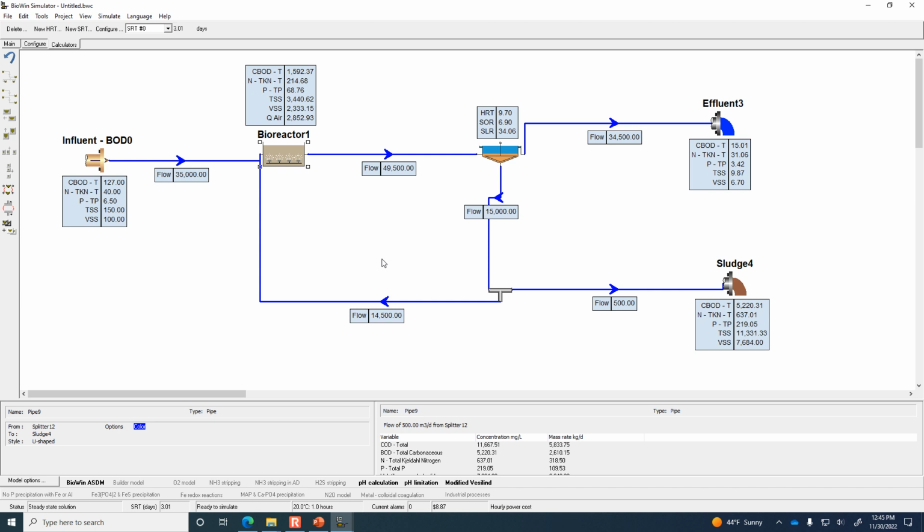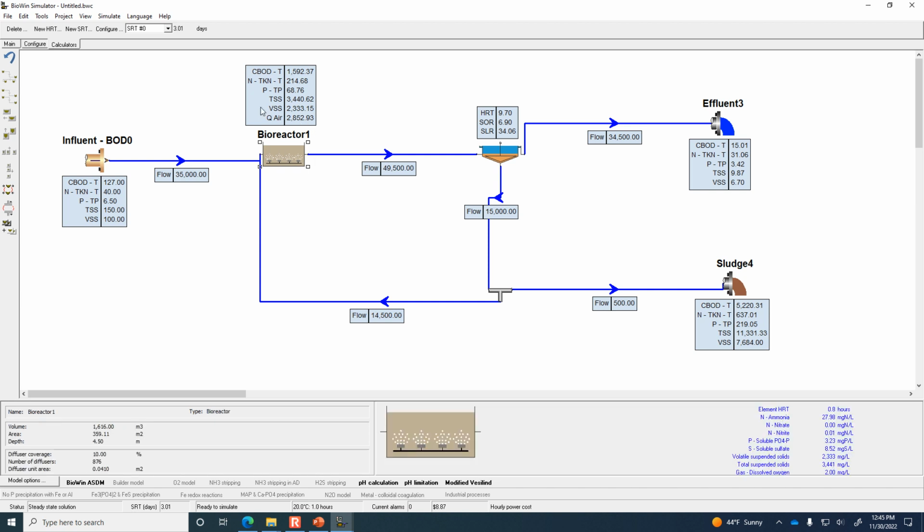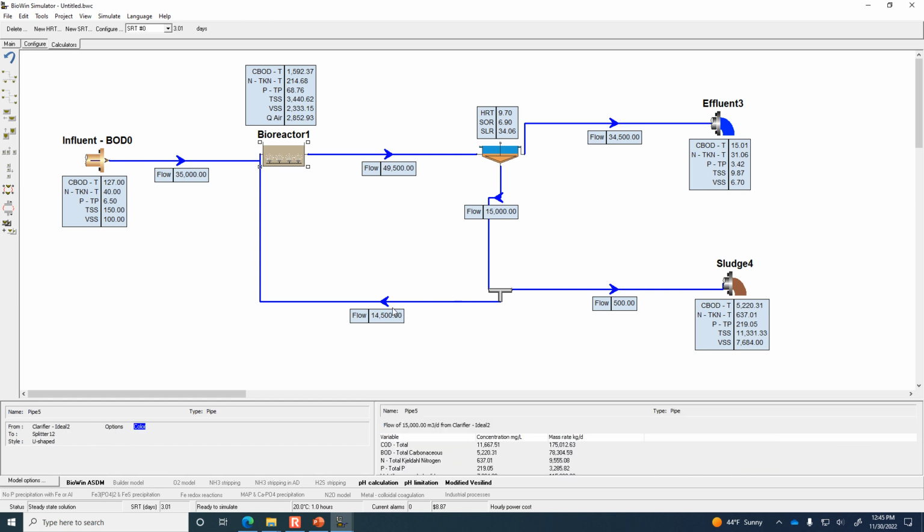In the background, it's running so many calculations having to do with aeration, because when I change the reactor volume, then the flow rate of air required also automatically updated. It's doing calculations related to the solids retention time. We are having some updated concentration of the volatile suspended solids. All of those things are impacted by having a smaller bioreactor where we've kept the recirculation amounts the same.